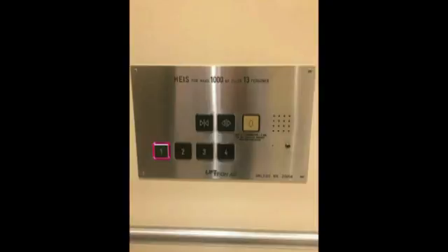Let's take an example of a lift. A lift will not be operational if the weight of the total people exceeds the maximum weight allowed in the lift. You can see a picture which shows the maximum weight or maximum people allowed in a lift. If the weight is more than 1000 kg, then the lift will not start. Also, if the sensor of the lift door senses an obstruction, it stops the lift from going up or down. This is a warning type Poka-yoke.